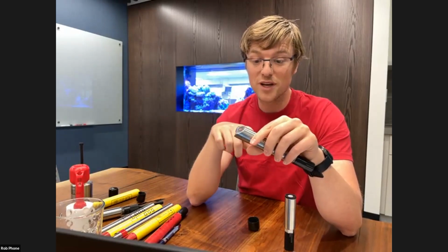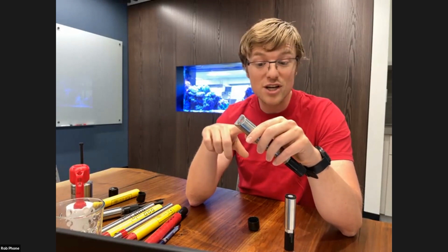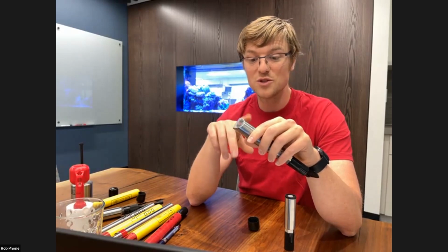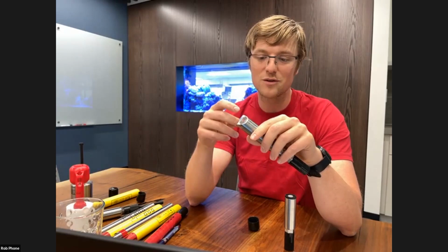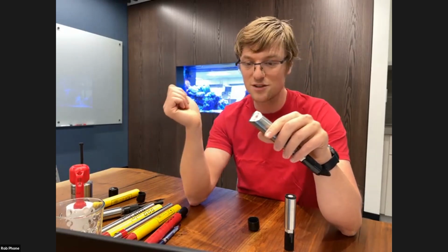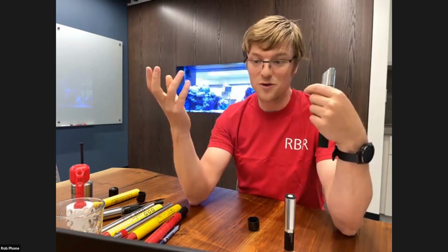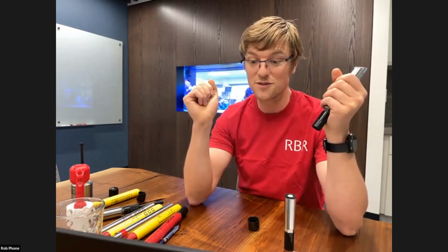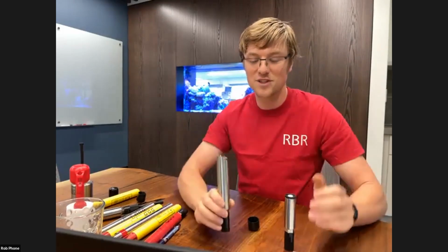In our construction, we have one LED that shines directly at the film, and another LED that just shines onto the photodiode. So we do two measurements, one with the LED bombarding the foil, and the second one where we just see the one that's internal. The two LEDs will age at the same rate, and their power output will change proportionally over time, so you can do a nice compensation there to ensure that you don't have drift on your sensor.